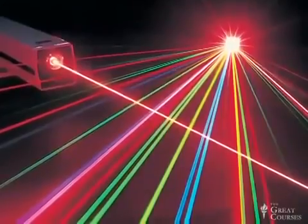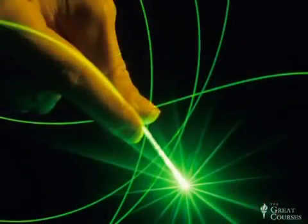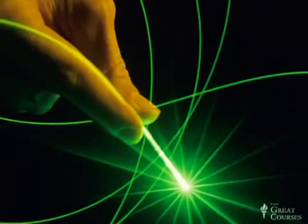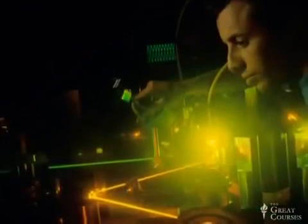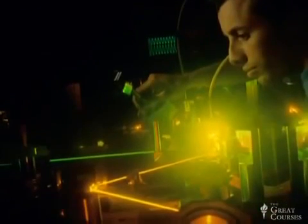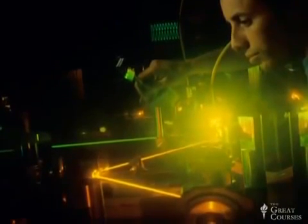Lasers, on the other hand, are famous for having exactly the properties that we're looking for. Lasers provide a beam of light having a single direction. And so they provide us with the opportunity to couple right into this direction that the light will be propagating down in the optical fiber. In fact, their beams can be tailored such that the range of acceptance angles of the optical fiber can be matched by the output of emission angles from the laser. Now that's one sense in which light from a laser is very pure or very perfect. It's the sense in which it's very directional.